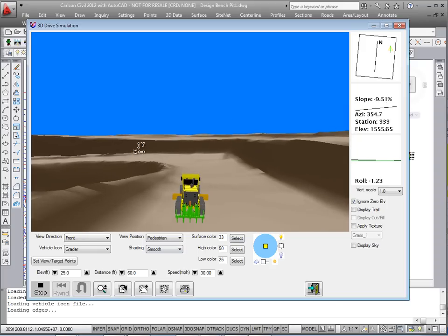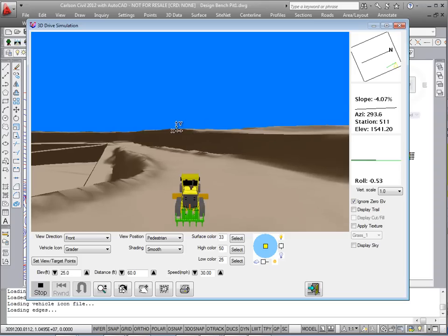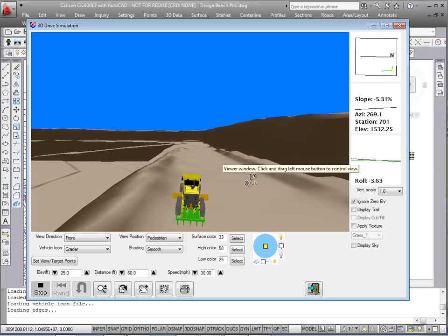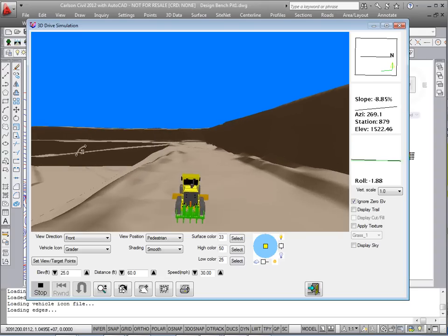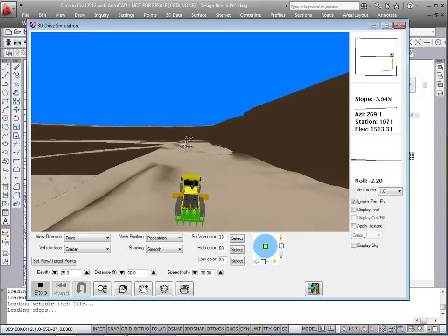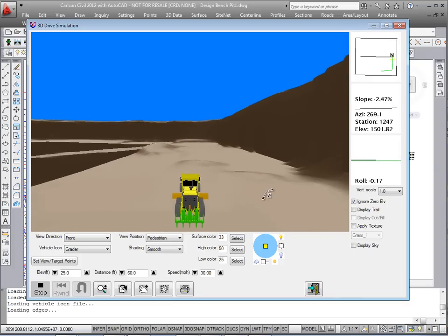There's different options for coloring, hatching, and if you have an aerial photo, you can drape that photo onto this 3D mesh so you're driving down through the photograph. So I'm coming down, and here's our new ramp design. As we approach the bottom of the original ramp, we should turn left again and go down this brand new ramp down to the new pit floor of 1400.